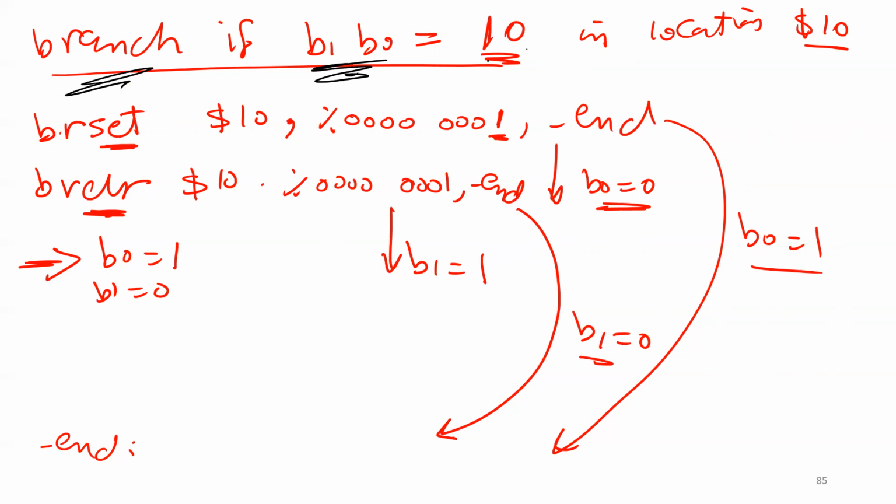This is different because all that I did before was with the 2 bits, all of them zeros or all of them ones. That's the instruction we have. I can branch if all the bits you want to check are zeros, or all of them are ones. We don't have an instruction to branch if one of them is 1 and one of them is 0. That's why I have to check 1 by 1. So I have to do it twice, as you see right now.